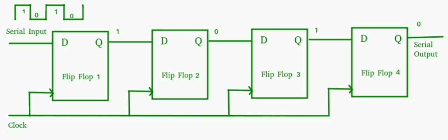Clock pulses required by various shift registers. SISO: input n, output n-1. SIPO: input n, output 0. PISO: input 1, output n-1. Whereas PIPO: input clock pulse 1, output clock pulses required is 0.